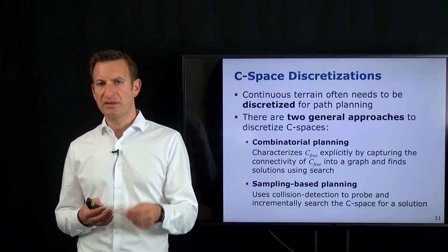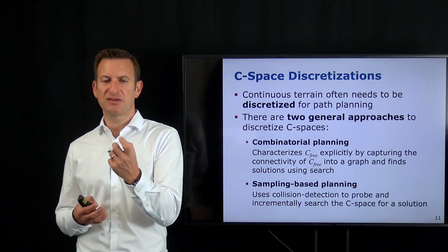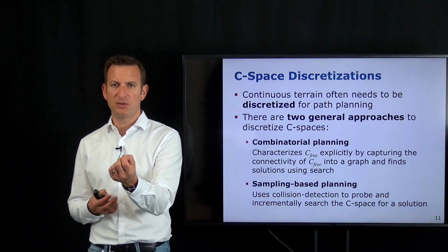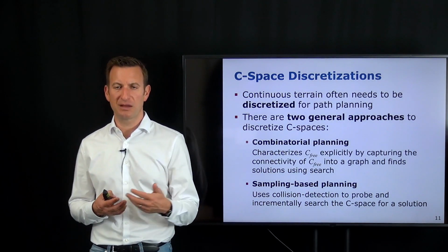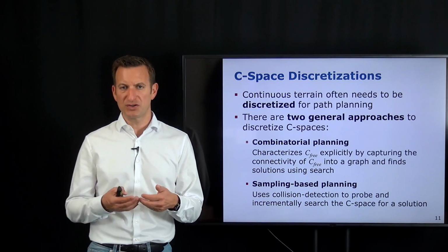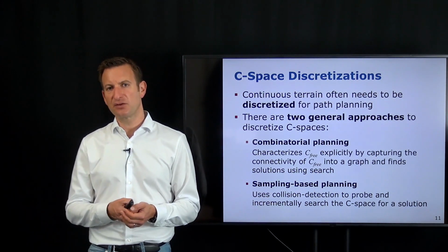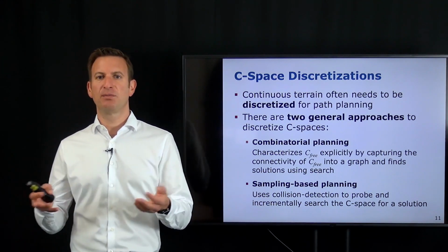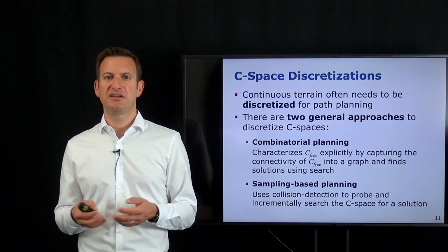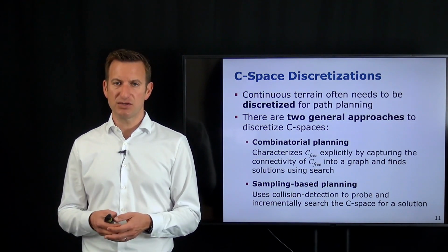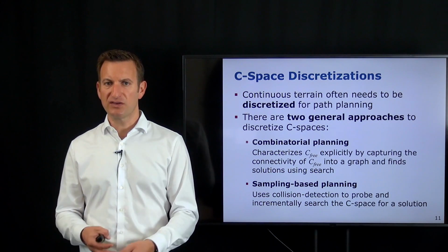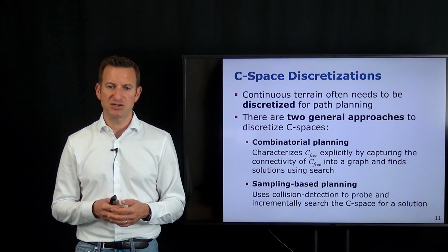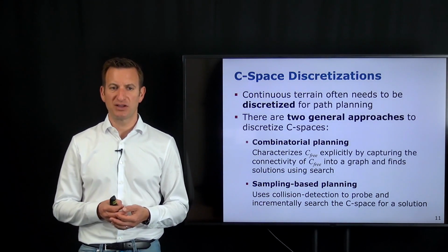And then with the configuration, the system samples something that is typically close to an existing configuration in the free space, and we have some way of connecting those nodes, for example, with a local planner or a collision avoidance check that can at least verify that there's a connection between those sampled nodes. And then I can sample nodes and in this way explore my free space until I reach my goal location. Of course, I can use things like heuristics or techniques which guide me or pull the sampling towards the goal location, because otherwise it can also be computationally very expensive.